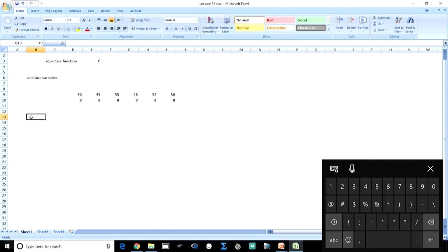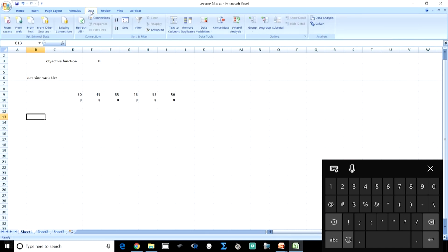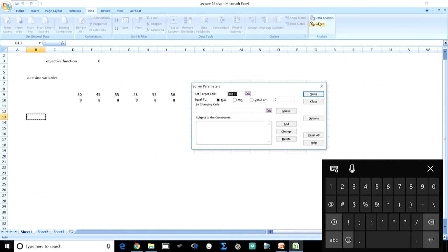So, therefore, right now the value of our objective function is coming 0; all those products and the summation of those products are giving 0 values. Next, we have to invoke the solver calculation, and then we go to the solver. In this solver, our target cell is E3.